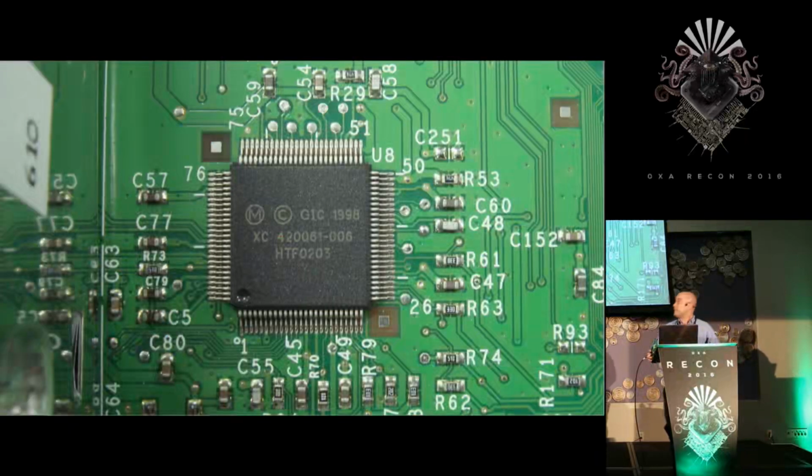This is the ACP chip. It's a 100-pin TQFP package. From the markings, we can see it's a custom system on chip made for General Instrument Corporation, GIC. All the decryption is performed by the ACP, and all decryption keys are kept only inside this chip.